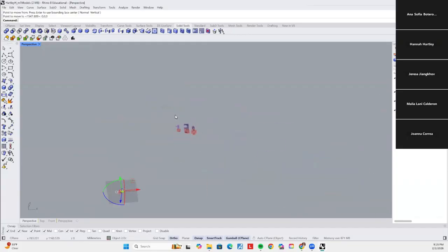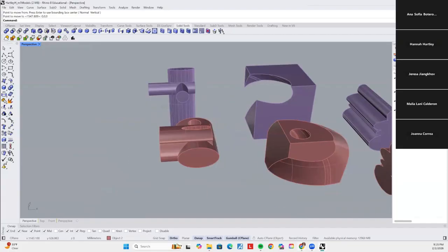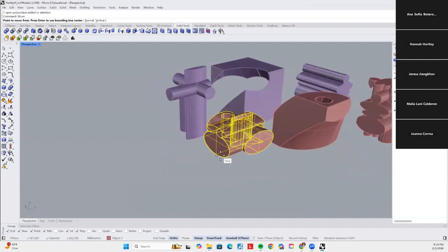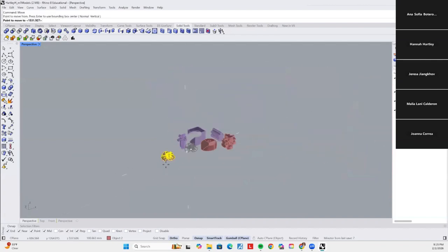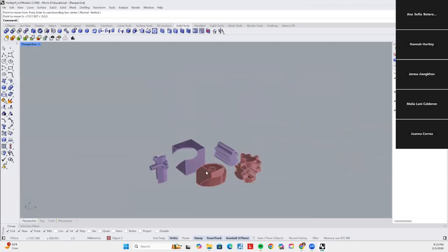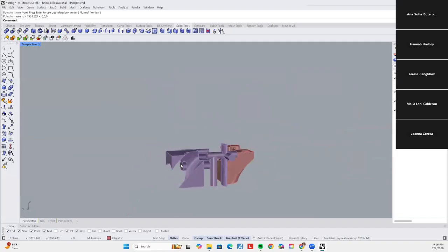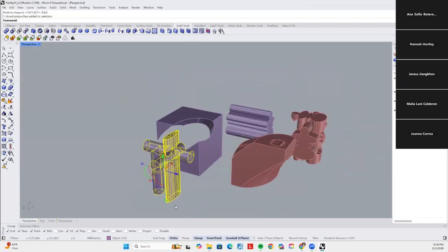And if it does, it creates something called support. If you've ever seen 3D printing supports, it kind of looks like really messy filament. What it does is help hold certain things that are going to be floating, like a cantilever or a roof or anything. Like for this example, it would need supports all down here. So when you're doing 0, 0, 0, you want to click the flattest side that you want to be laying down.